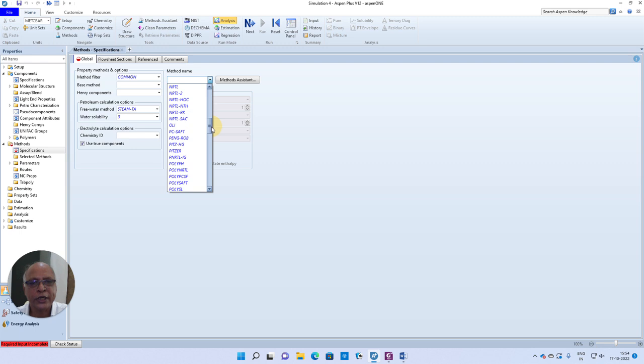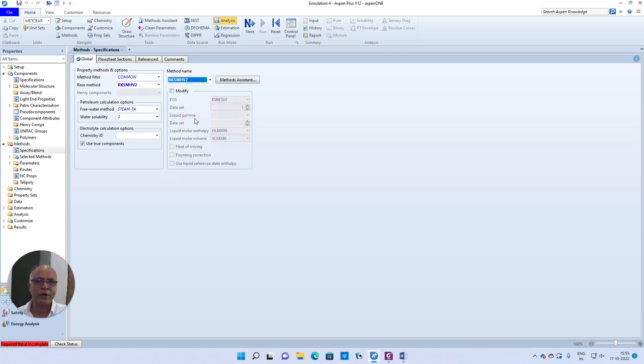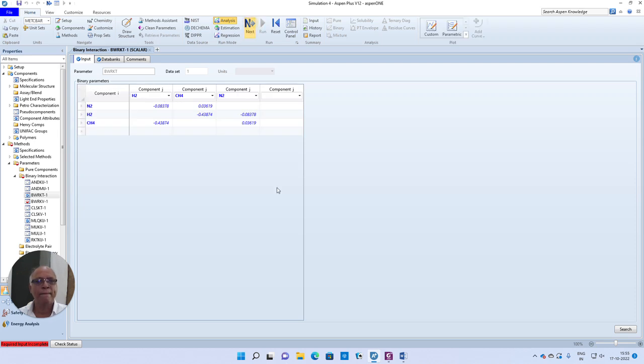So the mixing rules will come into the picture. Let me check. A model with the mixing rule of Huron and Vidal, right? So I'm selecting this. Generally, you are supposed to take some model representing the mixing rule for estimating properties, usually at high pressure. So let me take this. Go to the next step.